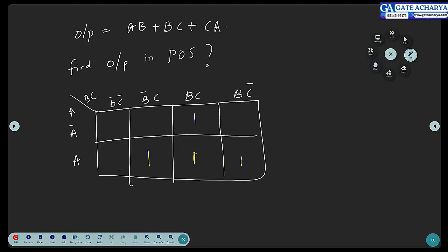So what are the skills we have discussed? First is, how does a K-map work? What is the magic it does in reducing Boolean expression? It tells you which term is redundantly needed to be added so that you can reduce it using the technique of A plus A bar is 1. Second, there are 2 ways to get a Boolean expression from a K-map, grouping ones and grouping zeros. Can you make a K-map from a Boolean expression? A very necessary skill. Now go through the questions.